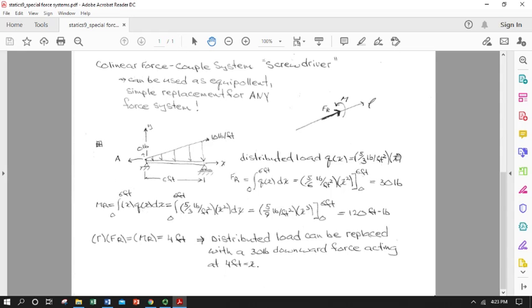So I can basically drop this same expression in here, plop it right in there, and of course I have another x multiplier, so my integral is a little bit different. I have a squared term, and so when I integrate it I end up with a cubic term. And then I evaluate between my limits and I end up with 120 foot-pounds, which is great because it's the right units.